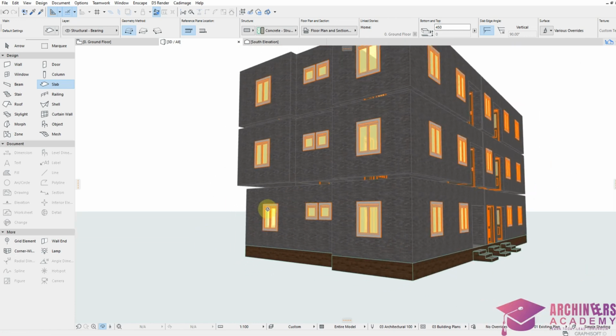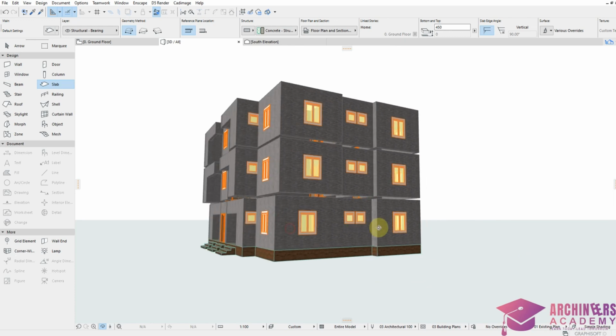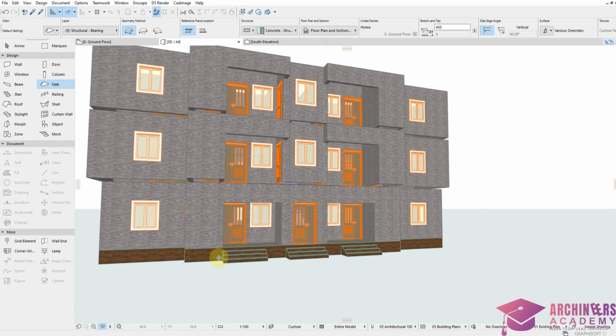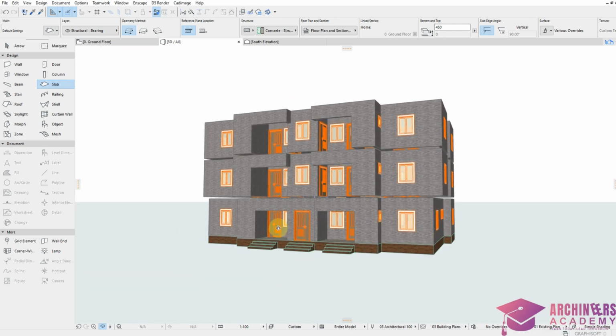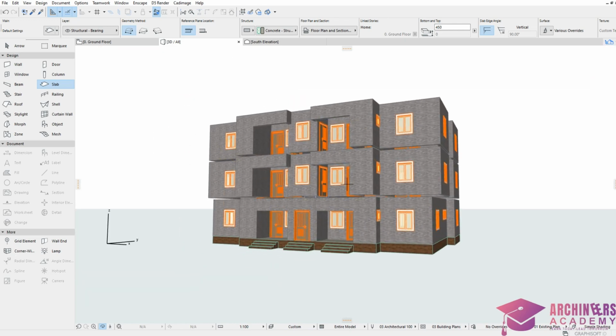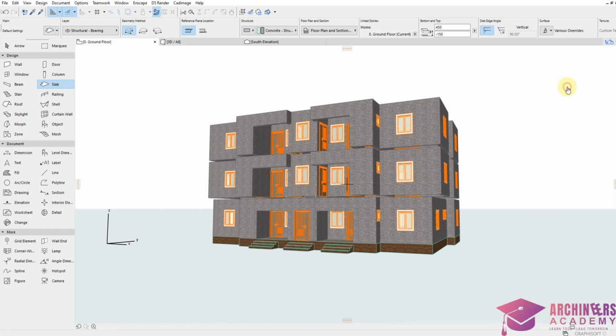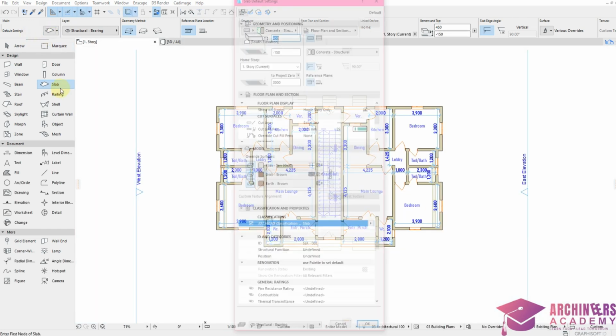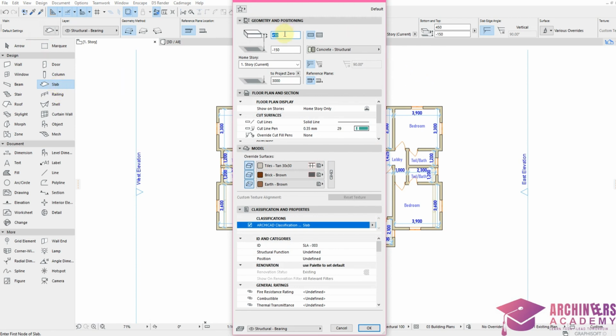I will now put the slab on the first floor and the second floor, since we have placed the DPC and the step. Then to put the first slab on the first floor, come over to first floor, which is first story. Once you open, then go to slab. Remember, it's already on slab. Open slab, then change the slab thickness to 150. It's going to be placed at 0.